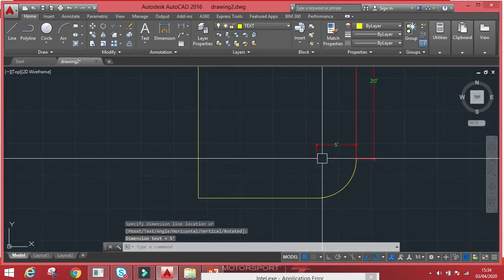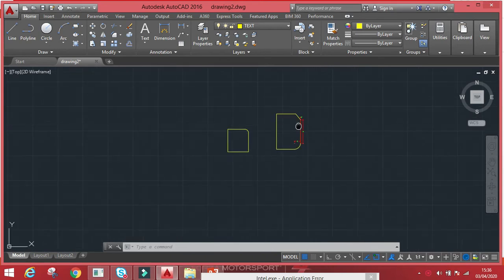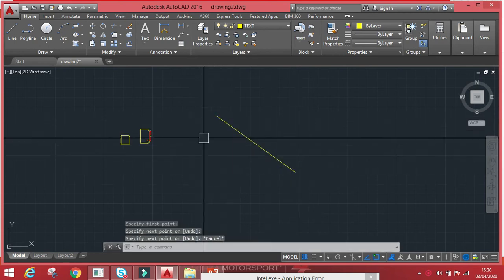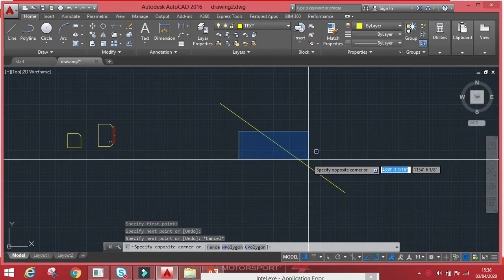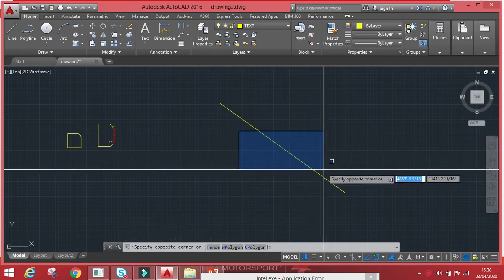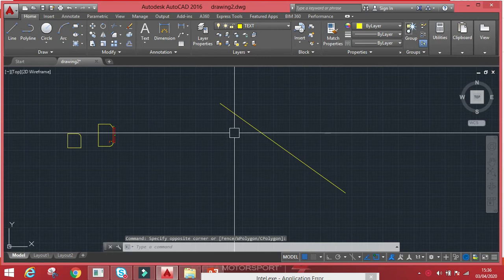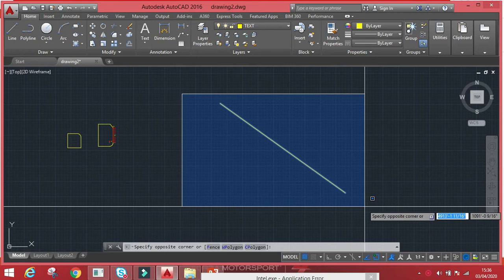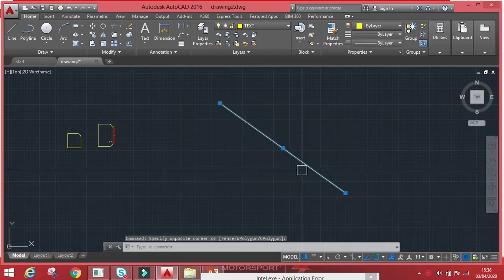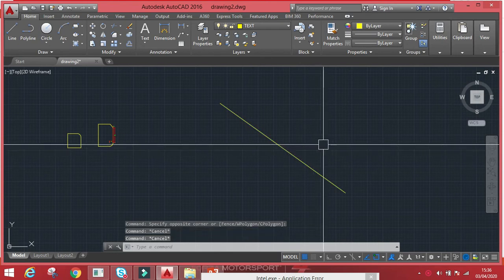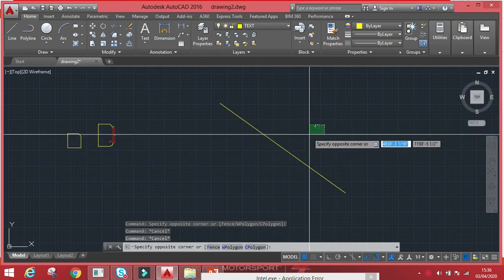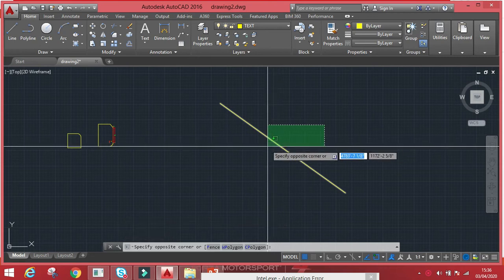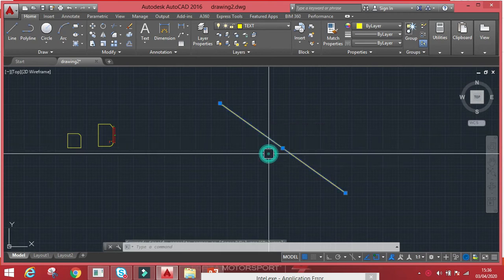So it's easy. We are going to discuss the selection process. So let's say if there's a line. Now observe, if I select it from left to right, then it's not being selected. In order to select it from left to right, I have to overlap this whole area above that line, the blue area. Then this line will be selected. Okay, what if I go from right to left? You can see that when I go from right to left, I just need to overlap a certain area. A small, minor area would do the trick to select that object.